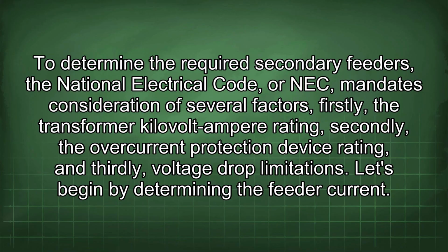To determine the required secondary feeders, the National Electrical Code, or NEC, mandates consideration of several factors. Firstly, the transformer kilovolt ampere rating, secondly, the overcurrent protection device rating, and thirdly, voltage drop limitations. Let's begin by determining the feeder current.